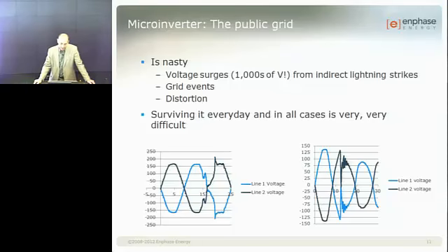And it turned out that there was a waveform, on the left there, where at 8 a.m. the substation was connecting capacitors for reactive power control. So at 8, they turn on a big, huge relay, and they connect a huge amount of capacitance on the line to optimize the voltage on the line. And every time this happens, it's pretty ugly, as you can see. And we had a little bit of a weakness that basically blew it up. So it took a while to figure this out. But anyway, it's life on the grid.